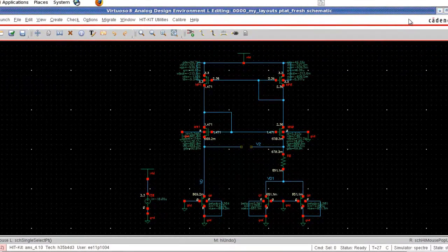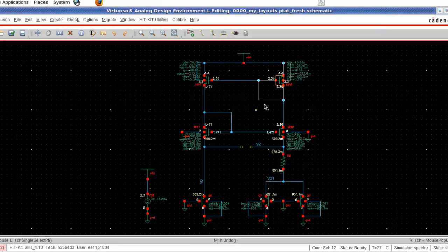For that I want the equal current to flow in the third branch. For that I am using the property of the current mirror, that is I am copying the PMOS, and I will connect exact same VGS to the PMOS, so that equal current will flow through all the three top PMOSes. That means equal current in all the three branches.